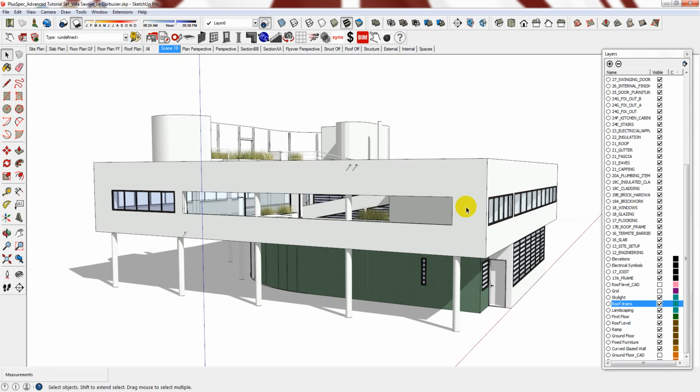There is also another way that you can control scenes, and you do this with styles. For the automated Plusspec scenes, a certain style has already been selected for you as a base template. However, it is up to you to decide how you want each scene to look, and you'll do this with the Style tool. For example, the Plusspec generated plans, sections and elevations use the hidden line black and white style. However, if this doesn't suit the way you want to present it, simply go onto the scene that you want to change and then choose another style type.